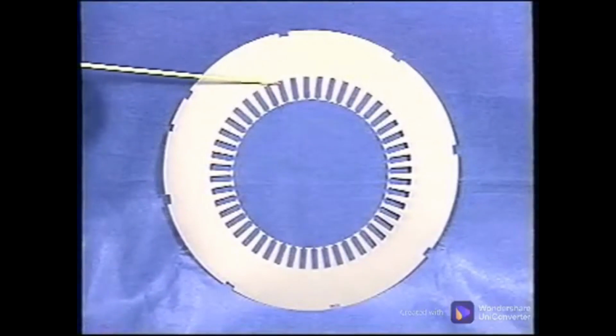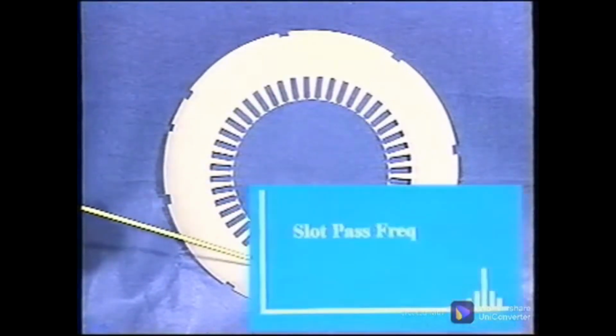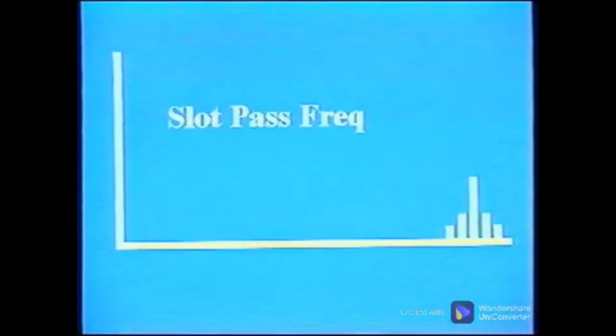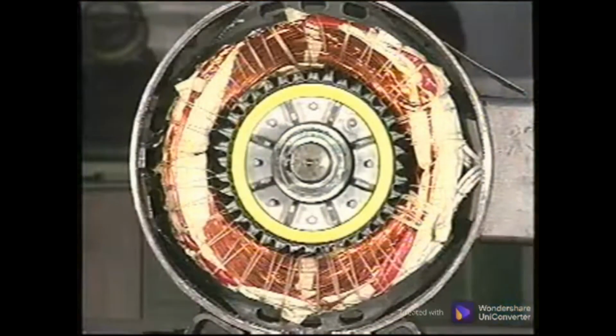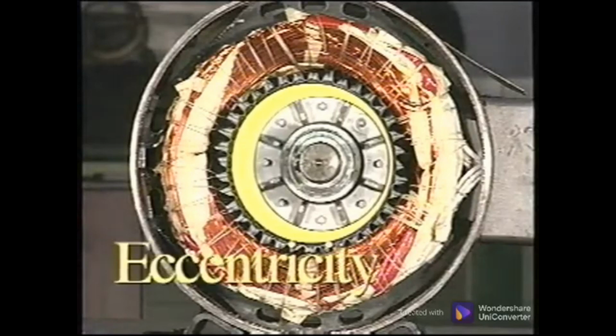Poorly designed stators will generate a pulse at the stator slot frequency due to the changes in the flux fields. This pulsing adds real vibration to the system, accelerating bearing degradation and shortening motor life. To have a uniform magnetic field or flux field, the air gap must be uniform. Any uneven air gap is called eccentricity.